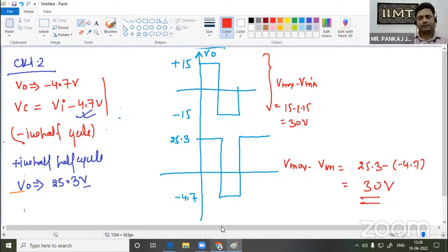So I am going to summarize: the first step is we have to choose that half cycle first in which our diode will be in forward bias condition. And most important thing, before doing any analysis, first we should confirm whether the question is clamper or clipper. In a clamper we will have one capacitor, one diode, and one DC battery to shift its input and output level. So a capacitor and one diode are essential components which must be there in any clamper circuit.